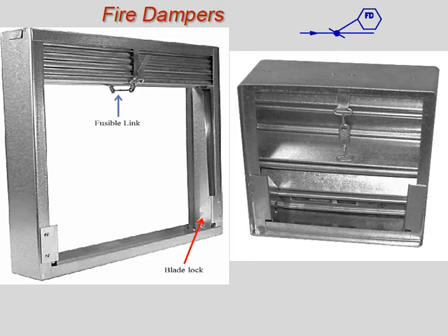A fire damper is a special purpose damper located in the duct as it passes through a fire barrier. A fire damper automatically closes during a fire. Fire dampers can be installed in either the horizontal or vertical position with coil springs. The spring provides a positive means of closing the damper by pulling the curtain shut.